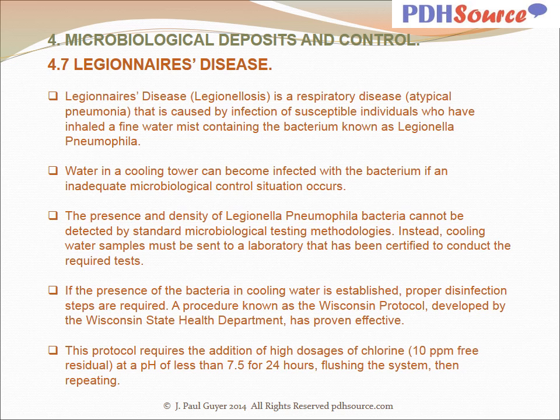The presence and density of Legionella pneumophila bacteria cannot be detected by standard microbiological testing methodologies. Instead, cooling water samples must be sent to a laboratory that has been certified to conduct the required tests. If the presence of the bacteria in cooling water is established, proper disinfection steps are required.